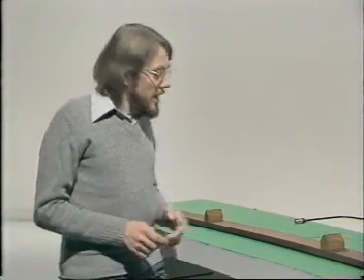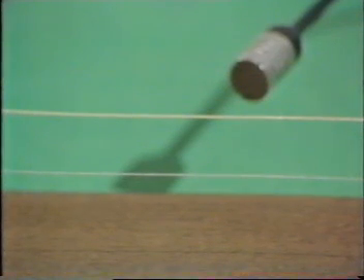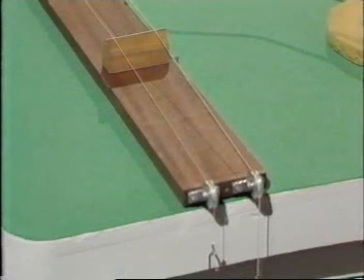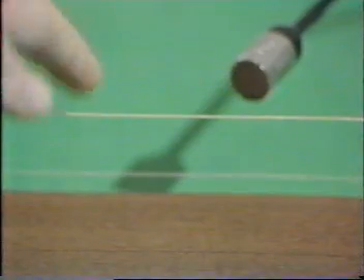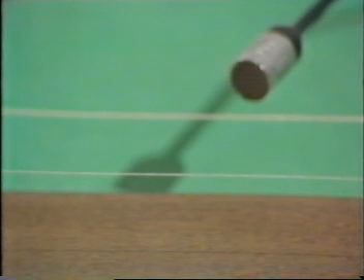What else affects the natural frequency of a string? Well, I've got a second string here now, and it's got a larger diameter, so it's got more mass, more inertia if you like. It's under the same tension as the original string, but compare the frequencies. The heavier string has the lower pitch, so the increased inertia slows down the vibrations. It reduces the frequency. The third factor that determines the frequency of the string, and probably the most important one, is its length.